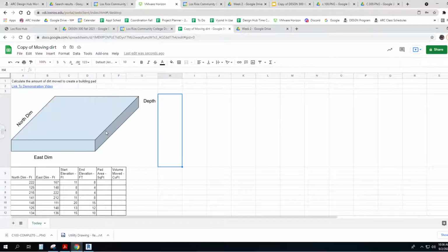Okay. But it's really important to know the volume of that building pad. And it's usually given by, if it's rectangular, a north dimension and an east dimension, and how deep your concrete is a certain depth, or the gravel and sand and colloid mix are a certain depth, or the dirt has been disked and compacted to a certain depth with concrete over the top.